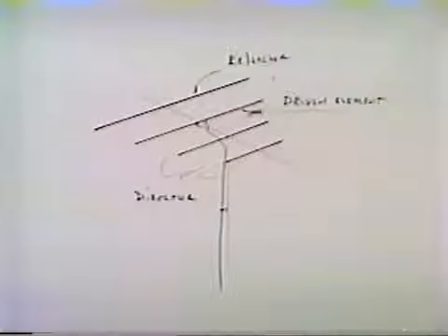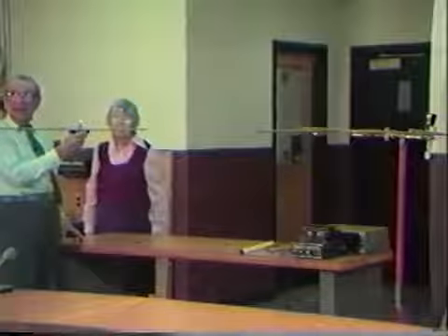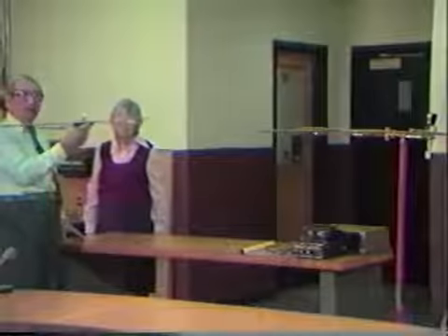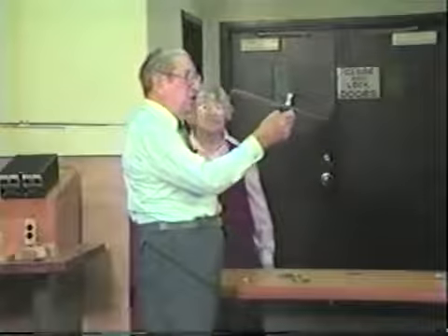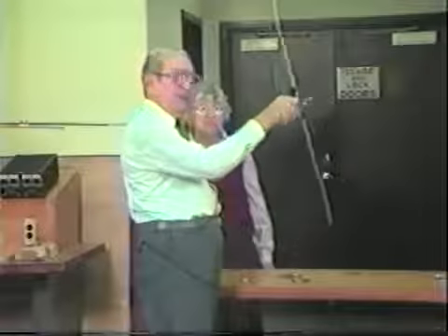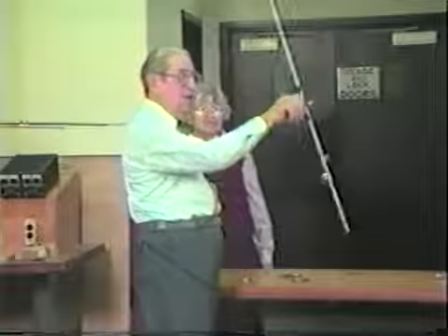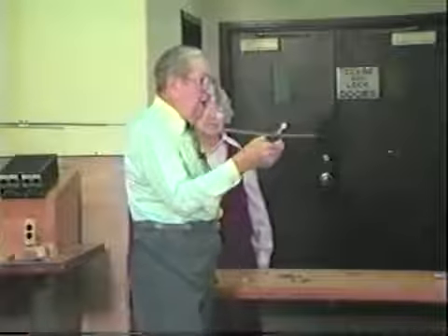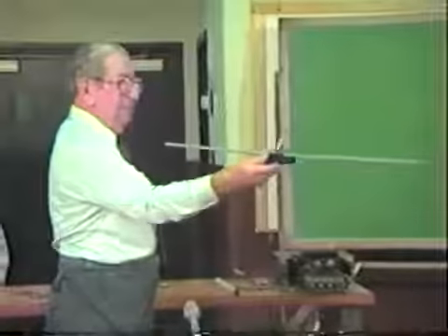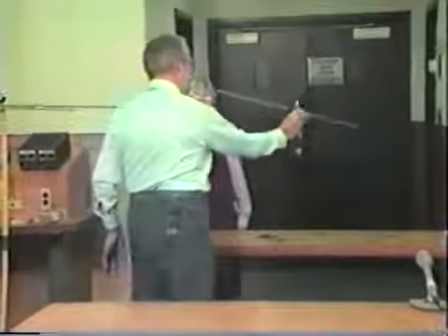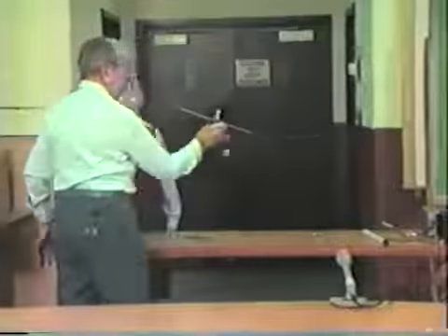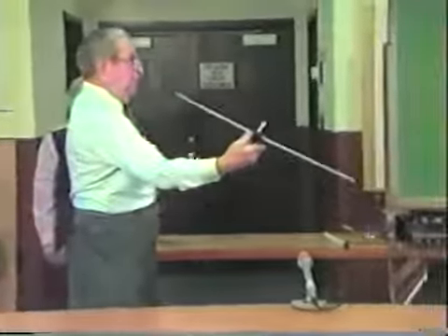And yet, I want you to notice the reaction of this antenna. I don't know whether you can see how bright this lamp is. You remember with the dipole before, I had to have it quite close to the antenna to get it to light up? I want you to look at this, and I want you to look at the polarization. Okay? Horizontally polarized. And you'll find that on this antenna, the signal will fall off on the sides. See it? Very sharp. You have to leave that on, please. Can you see it? So we have a very forward loop.